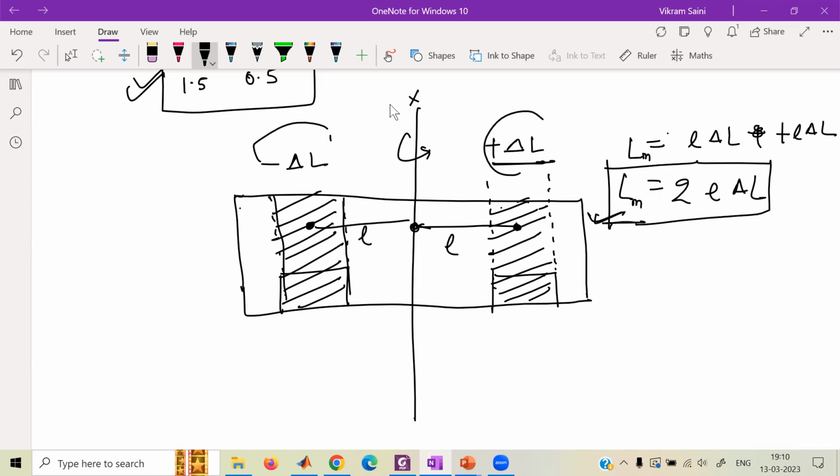So that will be the moment generated when you have deflected the aileron. The aim was to generate roll moment by deflecting ailerons differentially, one goes up, one goes down. So on one wing, lift goes down, and on the other wing, lift goes up, and you have a roll. Mathematically we have to find a relation: you deploy this aileron by some angle, let's say 2 degrees. How much roll moment will be generated is the question. How do you formulate this problem? We did it earlier.